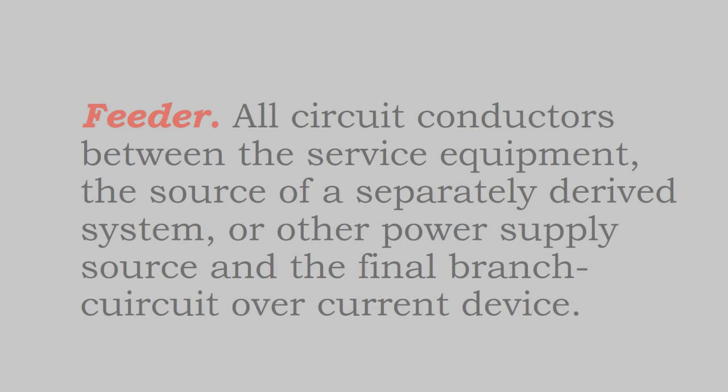That's a feeder circuit. Similarly, your grid connection is the same. It's from the grid to your main service panel. That's a feeder circuit. So from power sources to the main service panel, the load panel that they supply, that's considered to be a feeder circuit.